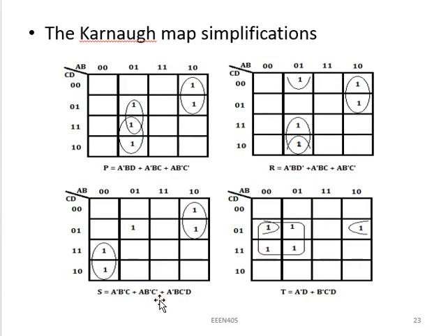Then I'll come to this one and say, okay, does it have anything in common with this or this? Yes, if you look at here, we have A B prime C prime, which is this last term. So since it is already obtained here, we also cancel it. So I can say I have 3 here plus 1 here, then I have 2 here because one of them is cancelled. So 3 plus 1 is 4 plus 2 is 6, and then these two, they don't have any as similar in any expression here. So I can say my product terms include 1 2 3 4 5 6 7 and 8. So I have 8 product terms.